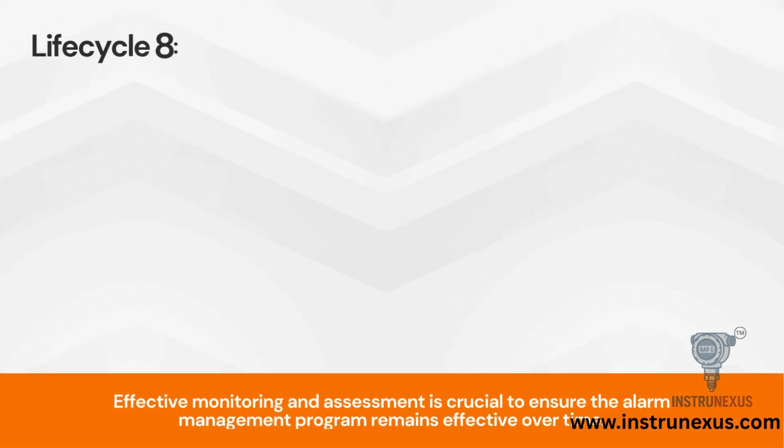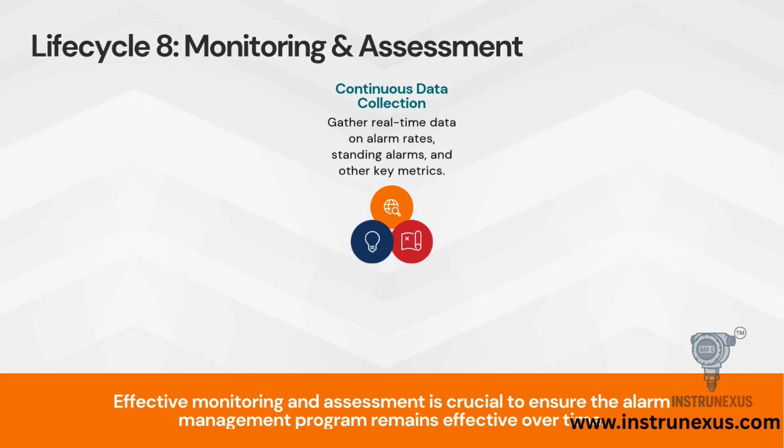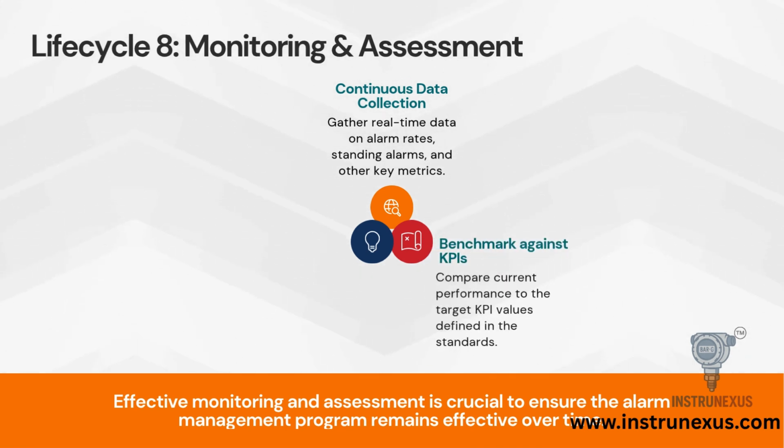Stage 8 is monitoring and assessment. You cannot improve what you do not measure. In this stage, we continuously collect data on alarm rates, standing alarms, and floods. We take this real-time data and benchmark it against KPIs, key performance indicators defined in the standard.